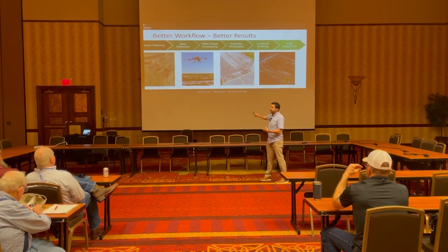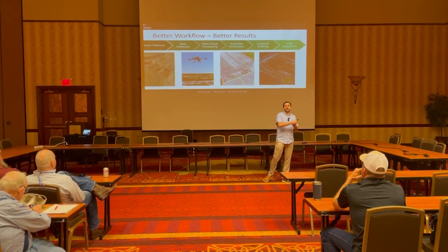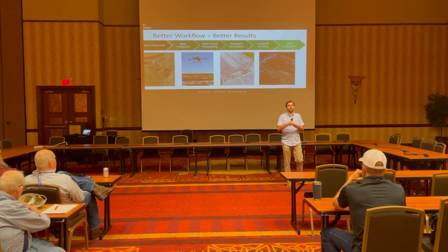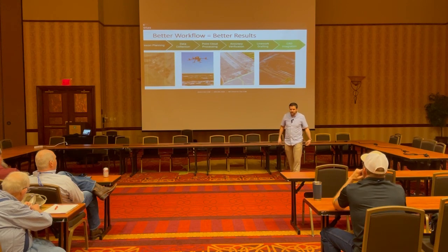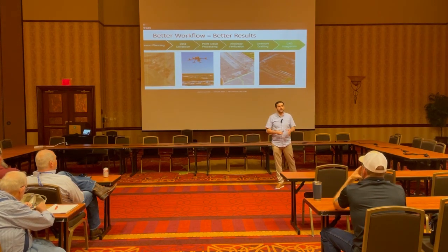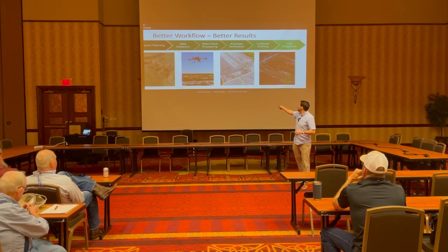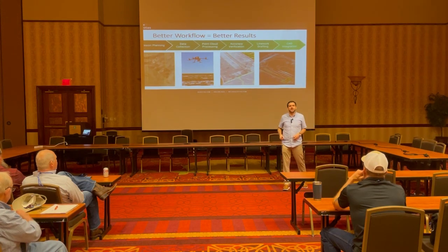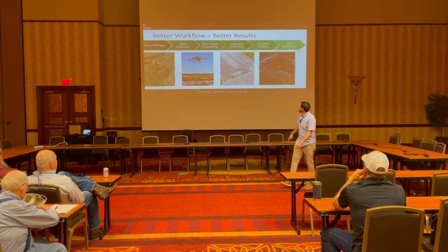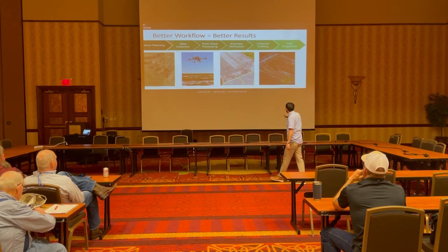Then we go through into point cloud processing. That's going to be whether it's with LiDAR, creating a LiDAR point cloud, or photogrammetry, creating your ortho photos, your DSMs, your point clouds, things like that. Going through that computer step is pretty important. Once you go through that and create all of your point clouds, what I often call the raw deliverables, the full resolution ones, then you want to verify accuracy.